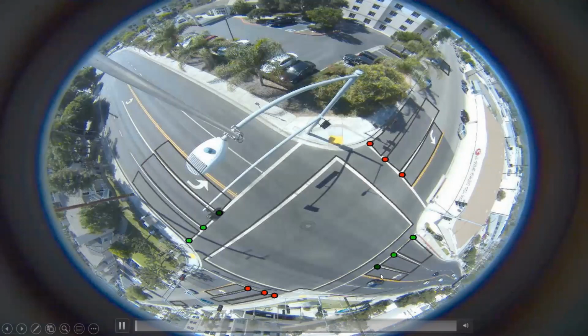All right. In this example, you'll see vehicles drive through the middle of the box. We've got the box drawn in the middle of the intersection, but vehicles are not actuating it, only the bike. And as the bike exits, the call drops, right? The outlined blue zone is determining that there's a call being sent to the controller for the assigned outputs.